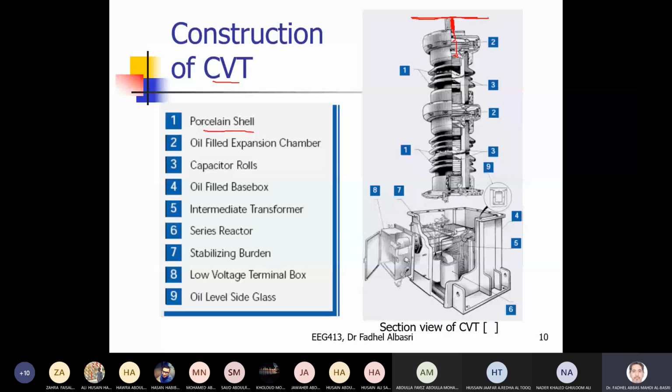Here we have a bank of capacitors inside. We have a tap somewhere here, which connects now. We connect this to a transformer. I don't want this voltage, I want a different voltage. This now represents, let's say, C1, from the top point to the tap at the middle, and this represents, let's say, C2. So this represents a voltage divider.